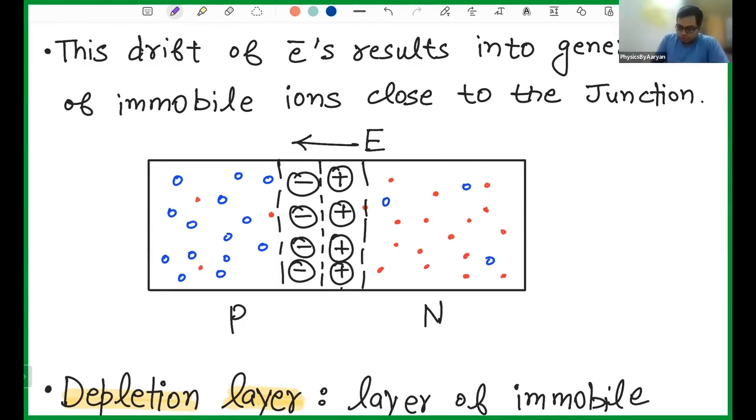Very good question. So what is the meaning of hole and what is the meaning of positive charge ion? Positive charge ion means that it actually has a positive charge. For example, I had the boron. Boron was completely satisfied. Boron was neutral. Boron had 3 electrons in its valence. It's completely neutral. Or you can talk about phosphorus. Phosphorus had 5 electrons in its valence and it was completely neutral. If I bring this electron out, then phosphorus became positively charged. So phosphorus is a positively charged ion. It's actually positively charged. But what about boron?